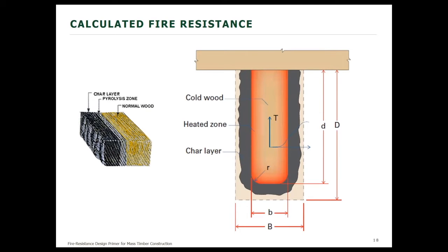What we have here is a graphic representation of the science and concepts behind the calculation of fire resistance. The diagram at the right shows how a beam with fire exposure on 3 sides is designed, ultimately based on the remaining unaffected breadth and depth after the desired time of fire exposure.